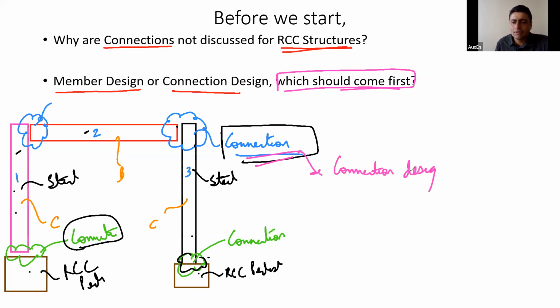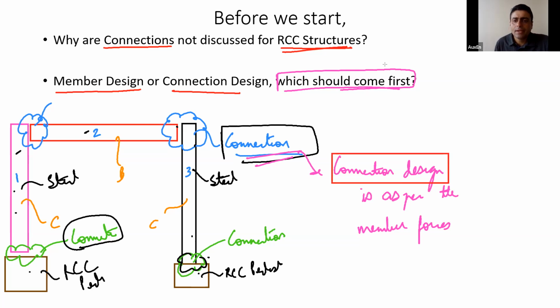I hope you agree, connection design is as per the member forces. So for understanding that a particular connection has to be designed for how much force, you need to have the member forces first. And how will you get the member forces? You will have to run an analysis, and from there you will get member forces.